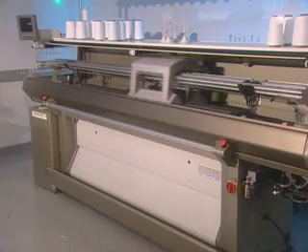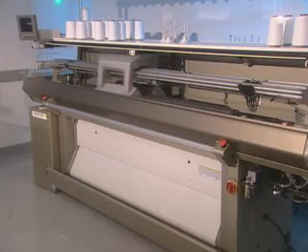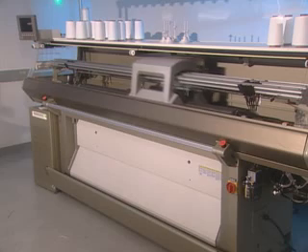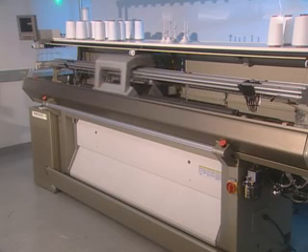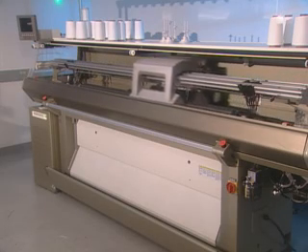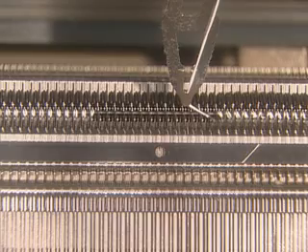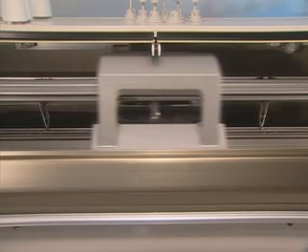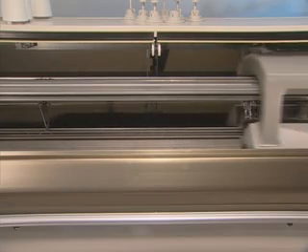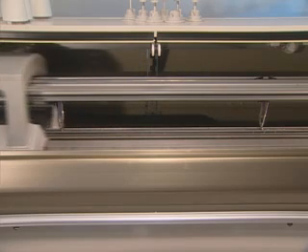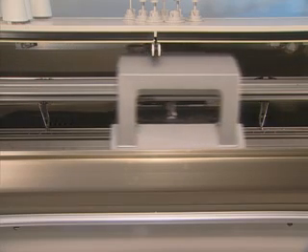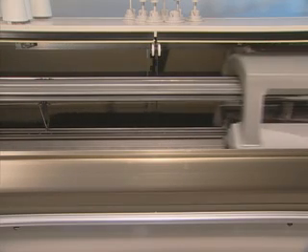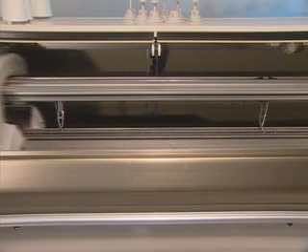A second type of machine can be used to produce a weft knit. This machine produces fabric on needle beds that are flat, resulting in its common name, the flatbed or V-bed machine. As in circular weft knitting, the width of the fabric is also determined by the number of needles being used, the stitch length, and the yarn size. Regardless of the type of machine used, in weft knitting, needles are placed adjacent to each other and knit in sequence to produce one course or row of loops from the same yarn.